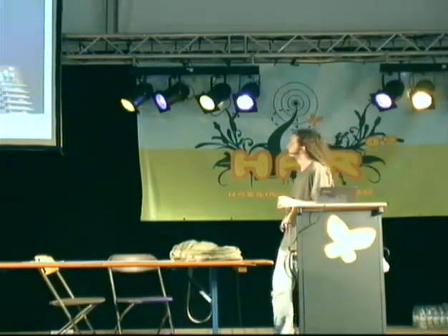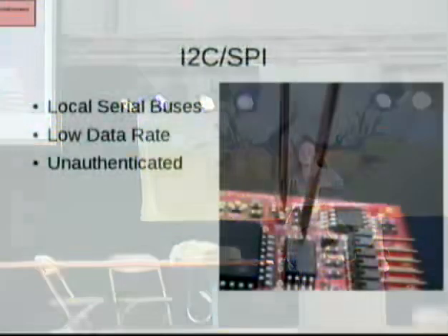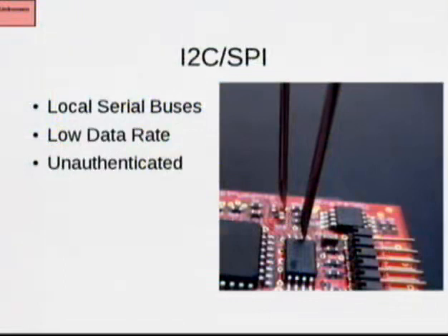And then once you've identified which pins and which rate and which protocol you want to use, you can stick hypodermic syringes into the board. These very quickly create a clean electrical signal with no soldering. Very few remaining marks will be on the device.